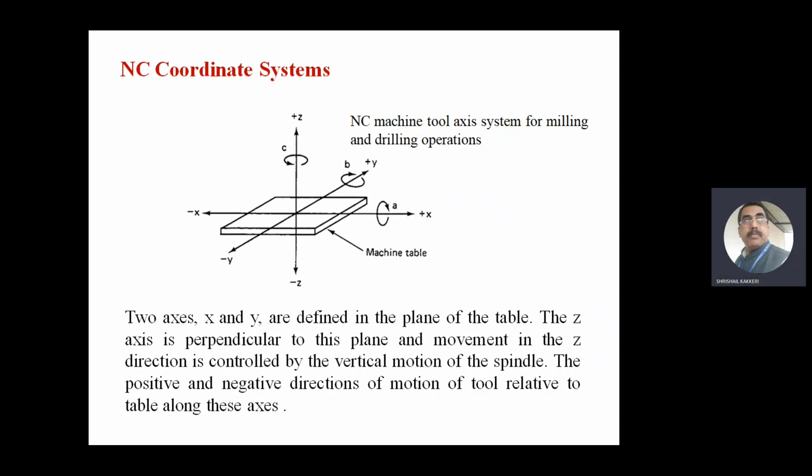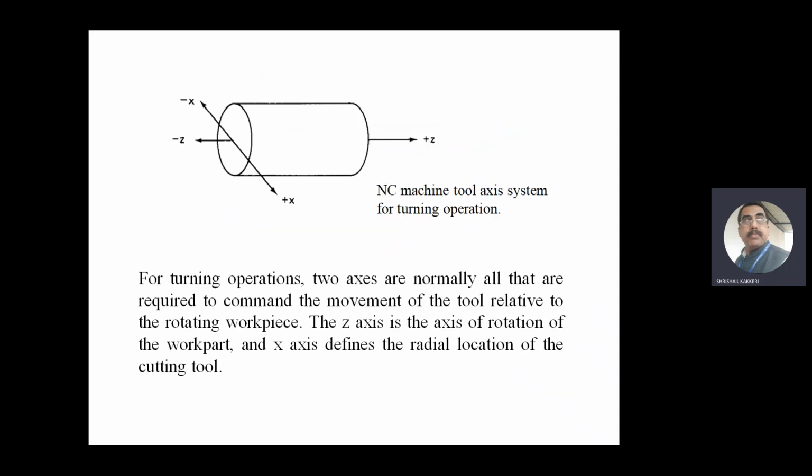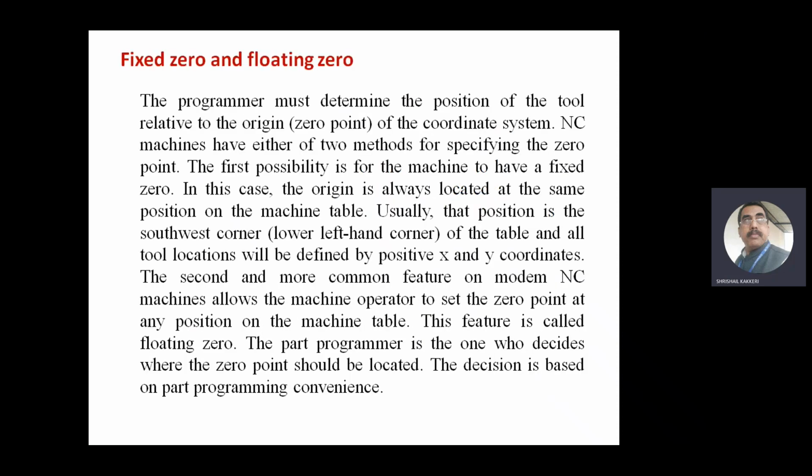Correct, no? And in case of the CNC turning centers, with a neat sketch, explain the coordinate system for the turning center and the milling centers. You can write, correct, no? Along the axis of the workpiece it will be z, and perpendicular to the axis of the workpiece it will be x. In some machines it can be called y also, but you say x axis only. Along the workpiece it should be z axis. These are the only differences we can find.